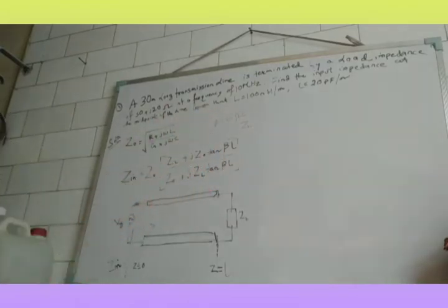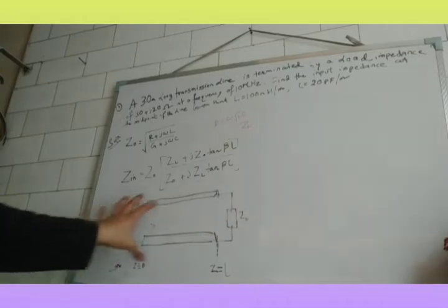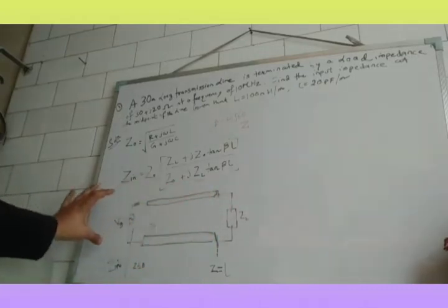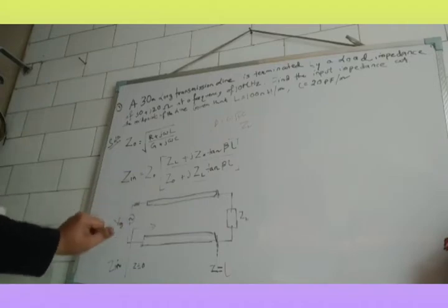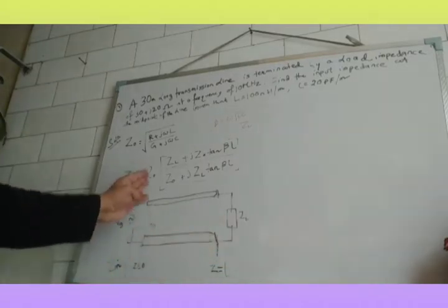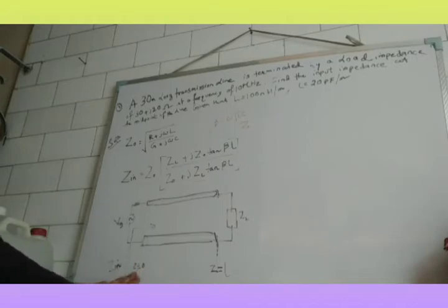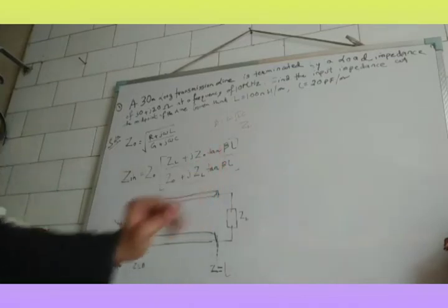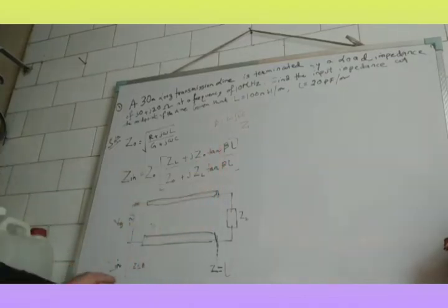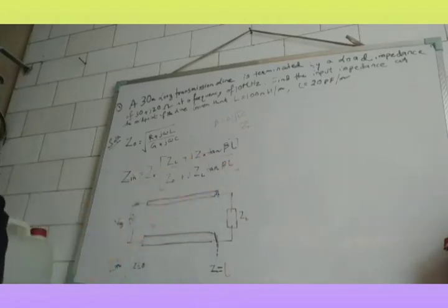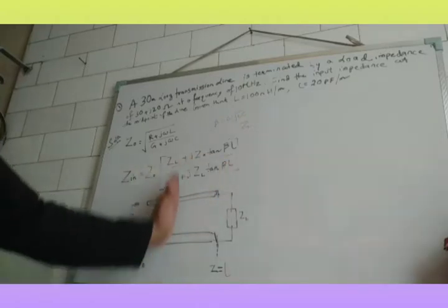So this is what I have drawn, a transmission line. This is a two-way conductor, you can say. I have applied a signal. This is the signal you are applying. This is the load end, and this point, let us say this is Z equal to 0, and from here we are calculating the length, and this is the input impedance which we are trying to calculate. Basically, we need to calculate this Z in at the midpoint of this line.